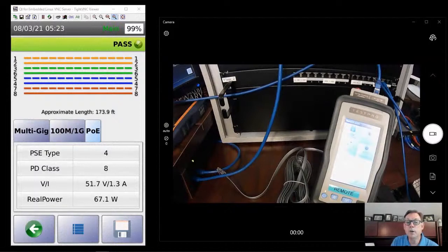Issues with the cabling itself, during manufacture or during installation, can cause resistance issues. A good example of something that can affect resistance is excess pulling tension. If you pull a cable too hard, you can change the geometry of the cable, and you can alter that copper conductor to the point where the resistance value will change, and it might change on one pair and not another. So any number of things could impact that.